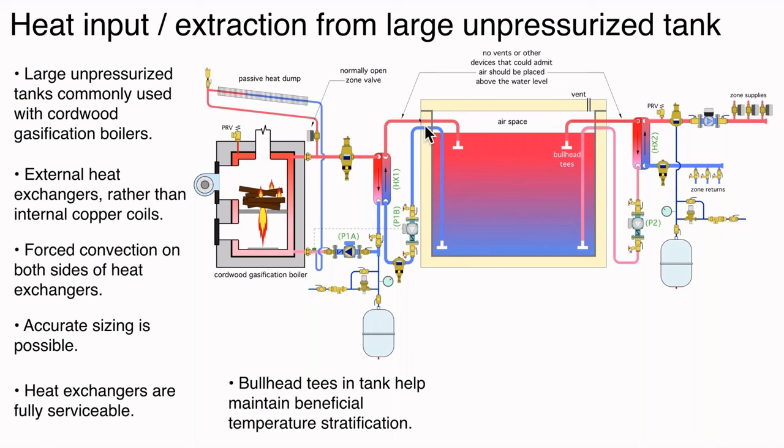And also it's important up here, no vents or valves, anything that could allow air into the system because this is atmospheric pressure right here at the top of the water. That piping that has water in it above that water level in the tank is going to be under slight negative pressure. And the water will stay in that pipe unless air can come in. If there's an air vent there or a leaking packing on a valve, that will let that water drain back out. So it's a small but important detail.